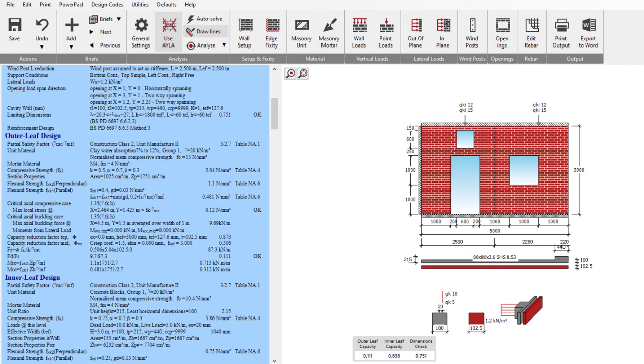How is base fixity achieved in practice, David? That is one of those eternal questions for structural engineers, and I could turn around and say it's not for us to say. We give you the tool to add in fixity or not. Certainly if you're using this in a multi-story configuration and you have continuity between floors, then it will be fixed.